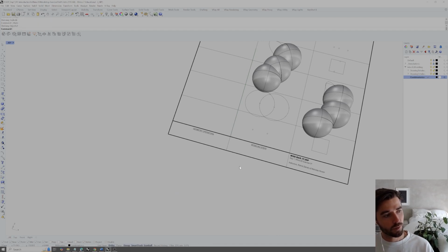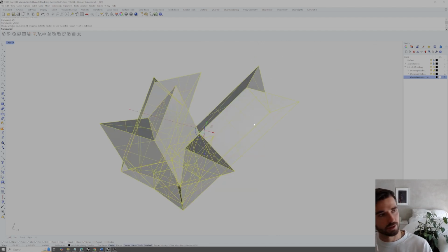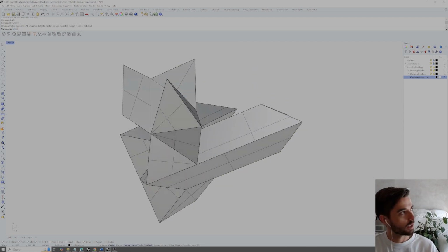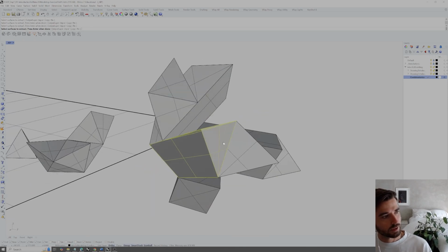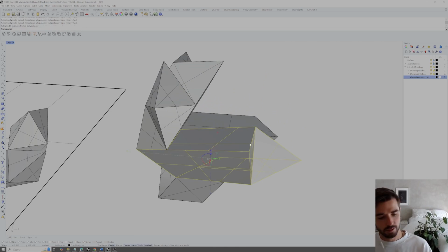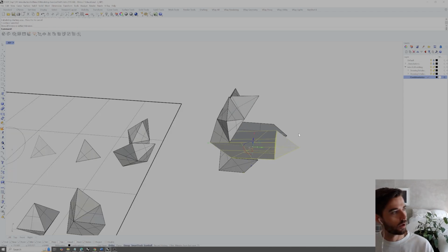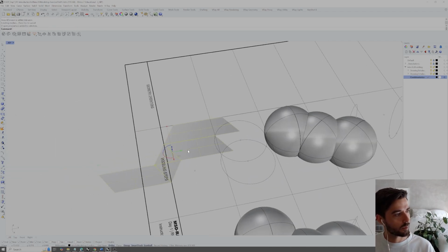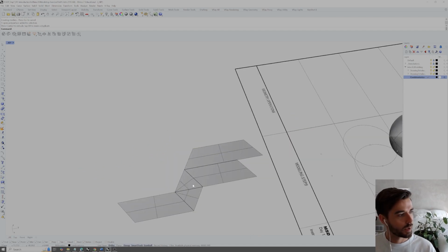A different way of going about it is from the very start, we can go into this geometry, we can use extract surface, and we can extract a number of surfaces. So let's say we can just do these to start. So extract those surfaces, join them back together, and then unroll surface, explode no. So now with such a limited number of surfaces, if we just pull this out here, we can see that actually there's no overlap, but they're still all joined relative to their three-dimensional edge joining pattern or organization, which means we can easily still fold it back up.